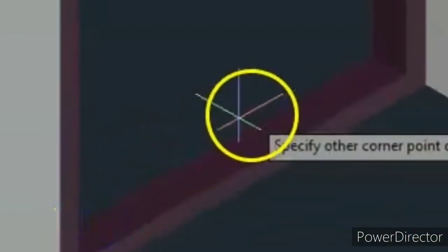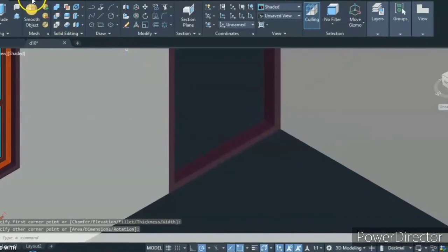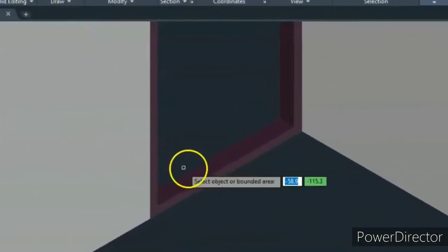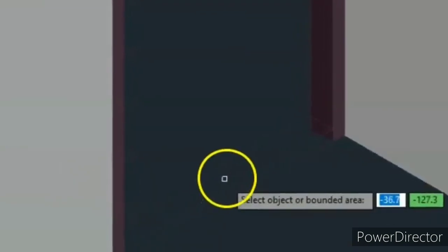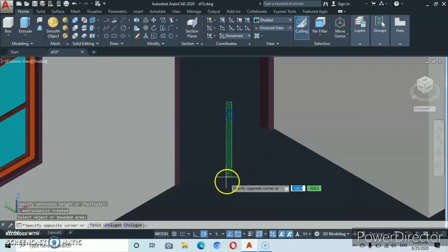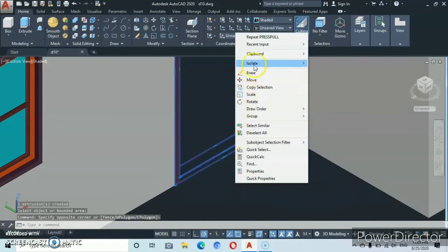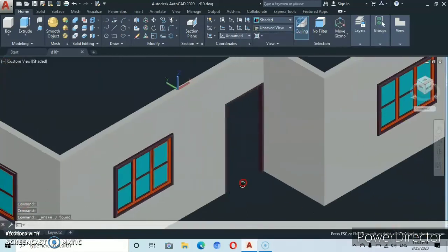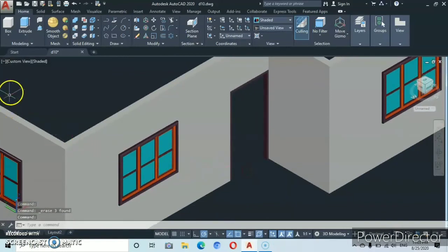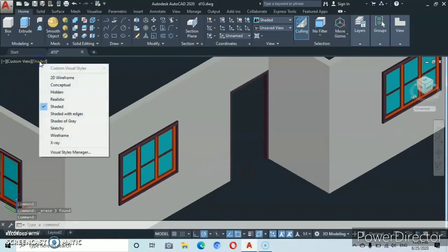Then now let's quickly go to rectangle, click on this endpoint, then we'll move to this other endpoint. Then now we'll go to press pull, then we'll click here, let's press pull downwards and have an opening there. We can now select this one and delete. Okay, there we are. Let's go back to visual style to put to wireframe.